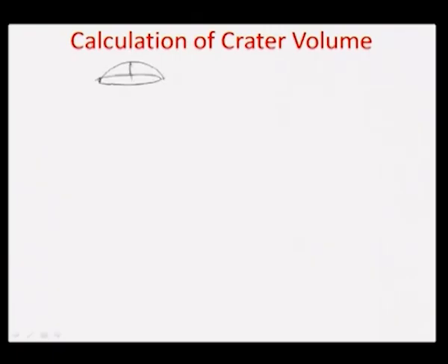This right here is the full depth of the crater Hc, and it is a part of this sphere here with center O, and basically we can consider a very small element like a cylinder in this particular area, and then try to see what is the volume of this and integrate such cylinders starting from the point A to the point B, okay, and we already know that B is defined by R, which is (a square plus Hc square) by twice Hc.